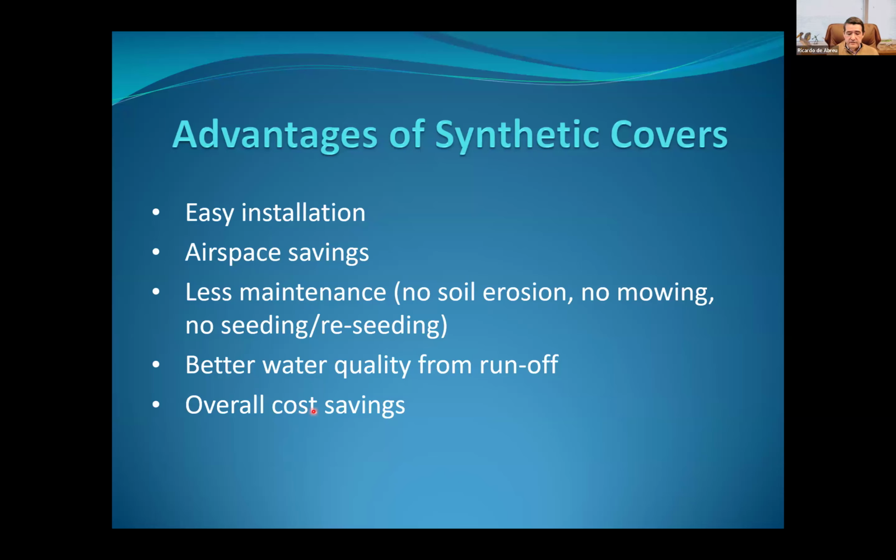Then the overall cost savings, not only sometimes on the installation, especially for places that don't have onsite clays for a final cover, but also the cost of less maintenance. That's significant, that you don't have to do constant maintenance on your final cap.